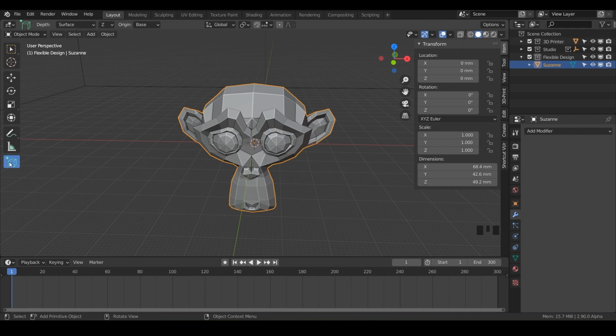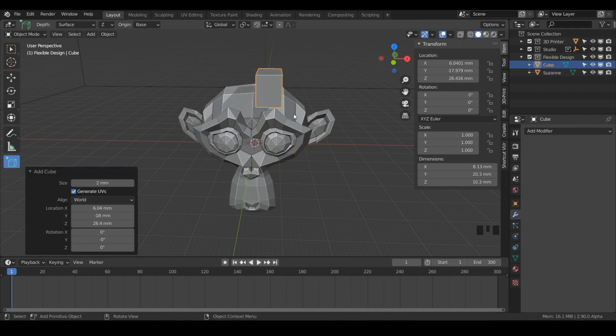So notice if I have this selected, I can click on the surface and kind of drag out a little cube here. And notice it's starting where I started the click, right there on Suzanne's forehead. And we'll scale it out. And then once I let go, it kind of confirms that square right there. And then if I lift up, it will bring up a cube. Or if I go down, it will do the opposite direction. So that's pretty cool. And once you click again, it will lock in that shape.